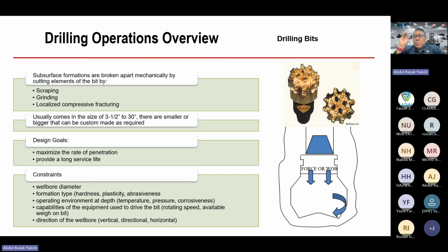Because if the drilling bit can cut nicely, but after like 20 meters it becomes blunt already, then I need to pull out. Pulling out is very, very long. Bringing it in is also very long. So that's the reason why, when I run in the bits, the bit is so important that it needs to last the entire whole section that you have over there.